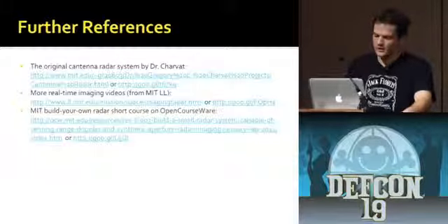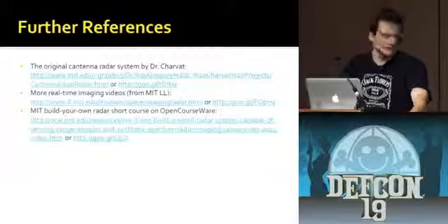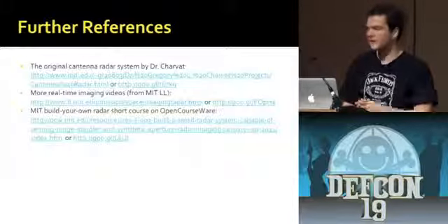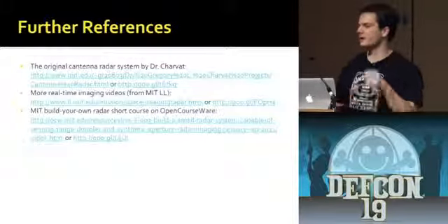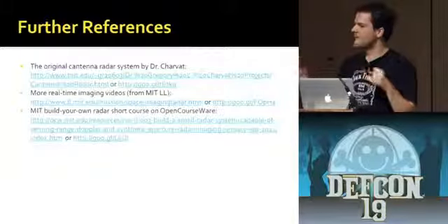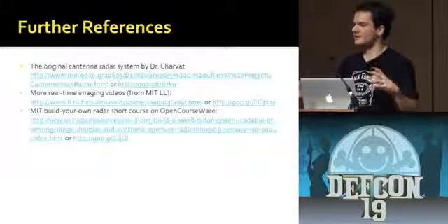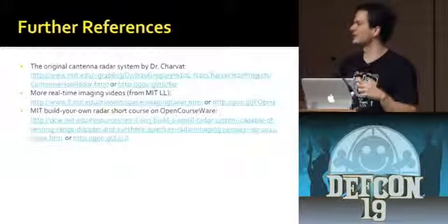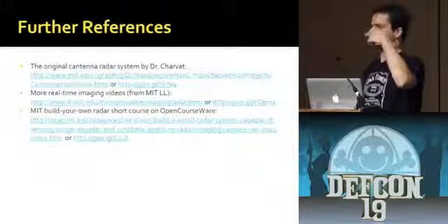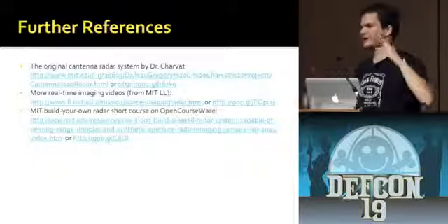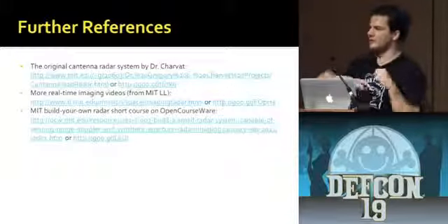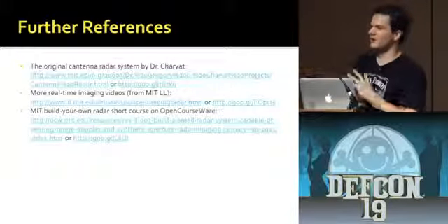Well, okay. What's the signal to noise with Wi-Fi? I guess it's pretty doable because with the Wi-Fi signals, you actually see the bursts on the spectrum. I was shocked I didn't see that today. I was sure someone was going to be using a Wi-Fi device in here, but basically what happens is you get these little blips in the signal, and that chirp is messed up. It's a pretty strong signal, and it's hard to filter out because it's not related to your signal at all. You're just basically sweeping right through it, and you pick up all that crap.